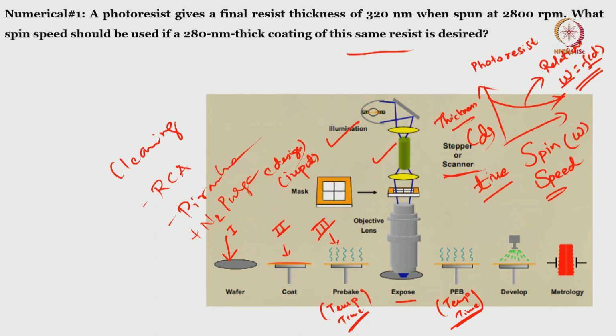So, this is your key input, the mask, and then the condenser lens I have already mentioned, then this is the mask, then the objective lens, finally some known optical sequential events happen and you will be able to get your desired pattern from mask to your wafer. So, this key step is the optics. So, this is again a very important key step. After exposure you will have a post exposure bake.